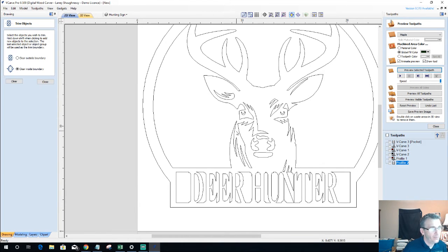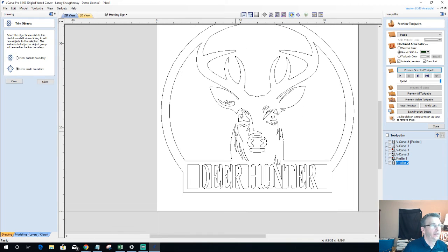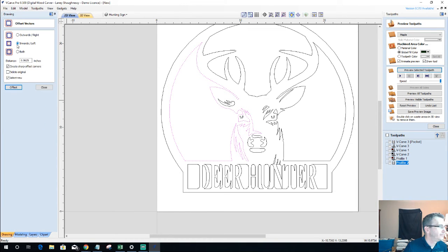Me personally, I would prefer it not do that. So what I'm going to do is take this half here and create an offset inward 1/16 of an inch. Not a 16th, that's too small. Let's go with a full quarter.